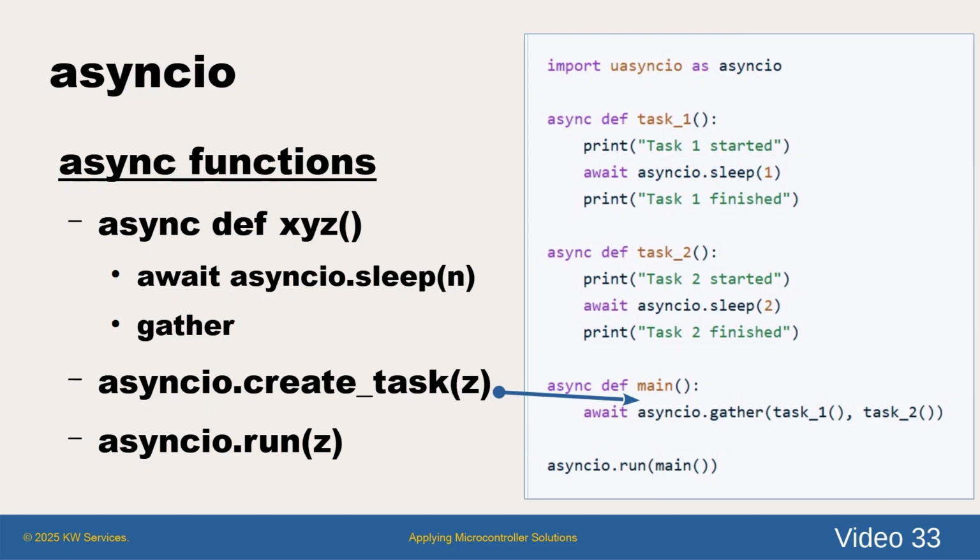The MicroPython doc explains that there are several async functions. First, you declare an async task by adding the word async in front of any callback function. Next, you declare a main function to register the async task by using the createTask function. Finally, the bottom of the code performs an async.run on the main function. This is the endless loop.